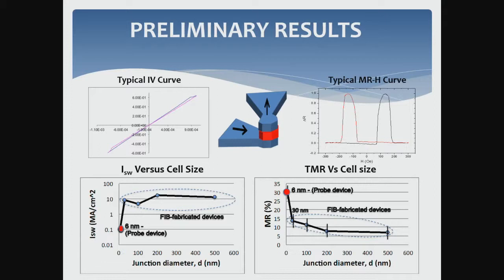Now here are just some more generalized IV characteristics that we find. Over here is a typical IV curve in which, as we increase the current, let's say from an anti-parallel state, we eventually switch the free layer until they're both magnetized, and we see the quick drop in resistance there. And then we retrace it back again, and we effectively go back to the anti-parallel state, defining two different regions here. The graphs aren't labeled here, but this is an I versus V graph right here.